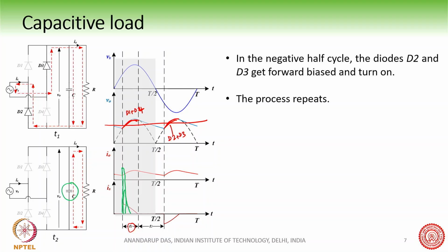So that is why the input current is becoming very peaky in nature, because it is trying to extract that energy which is required by it. It is drawing a lot of energy during a small T1 period, which it will deliver to the load during a bigger T2 time period. A short intake but a long output time duration for the capacitor. And during that short period, because it is taking a lot of energy, the current must go high. So therefore the source current is very peaky.